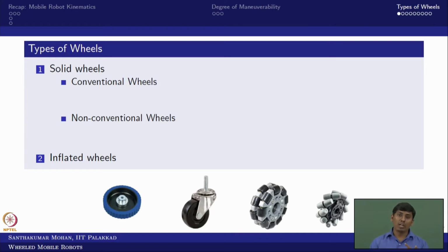Now the passive roller direction, you can say the axis. The passive roller is marked here in black. This black roller, you can see the hub is here, and the black roller's longitudinal axis is perpendicular, right? Although it is not intersecting, it is perpendicular. Now in this case, the wheel hub generates the traction. So at that time the wheel will go in the longitudinal direction, whereas even if you push in the lateral direction, you can see this passive roller will roll.